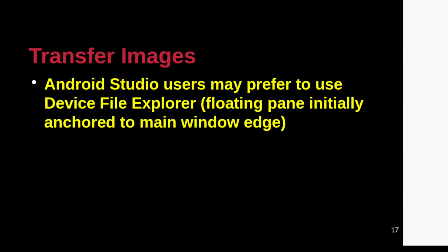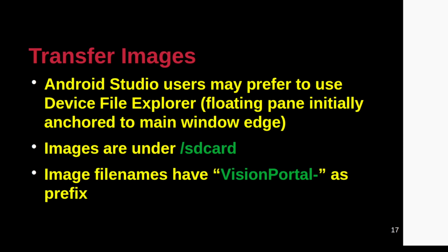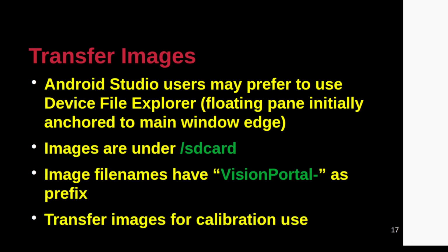The op mode utility camera frame capture will save the captured image to the folder /SD card on the control hub. All captured images have the prefix Vision Portal for the file name.